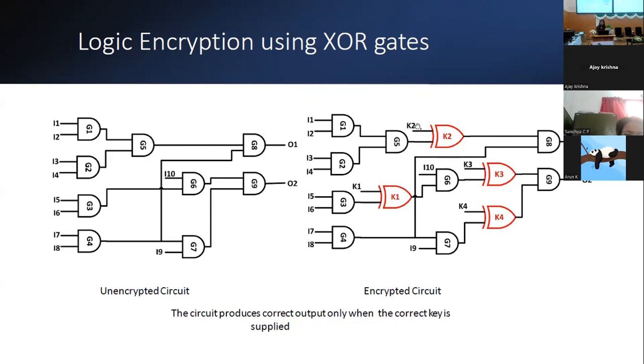This key bit I should give properly. Okay, this is called logic locking. The simple one: I have a logic circuit. I lock it by inserting some additional gates. Those additional gates are controlled by external bits. Those bits are called key bits.